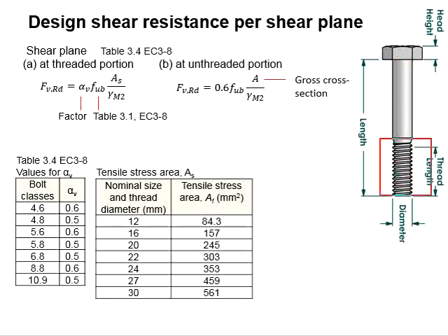As the threads are normally carved from the unthreaded area, the effective diameter of the bolt for the threaded length after carving is normally smaller than the unthreaded. With that, the effective areas of the unthreaded portion and the threaded portion are different.